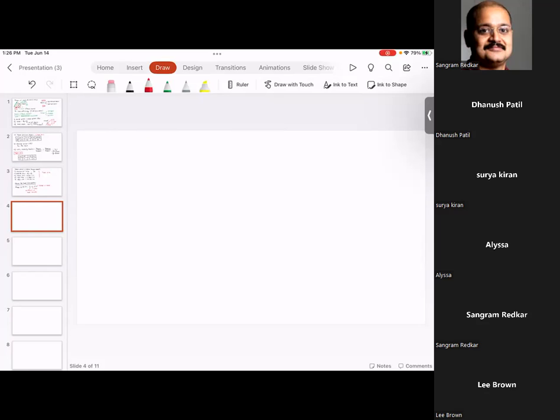One thing I want you to understand is that whenever we are designing, the worm is usually a very strong component, because the worm is cut from a solid shaft. The wheel is weaker than the worm.